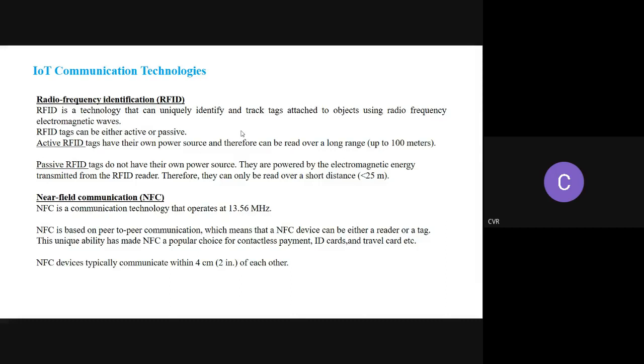Then you have NFC. You might have seen it commonly; it is there in your credit cards or debit cards, and even office IDs. It is very near field communication, and it operates at 13.56 megahertz. It is used in peer-to-peer communication, so it can be a reader or a tag. It supports only very short distances, so that's why it's used only in this kind of application.